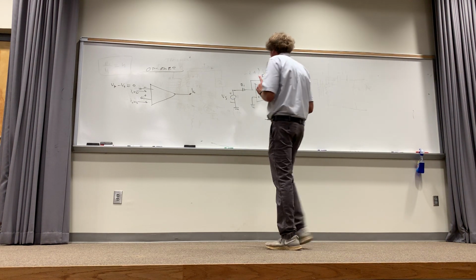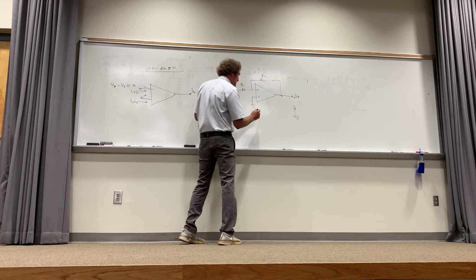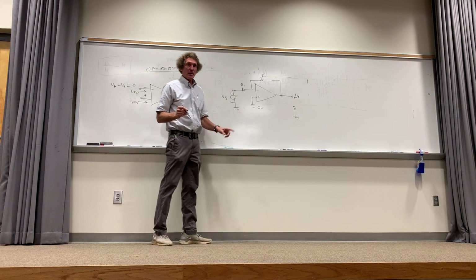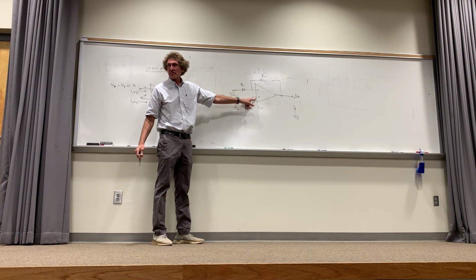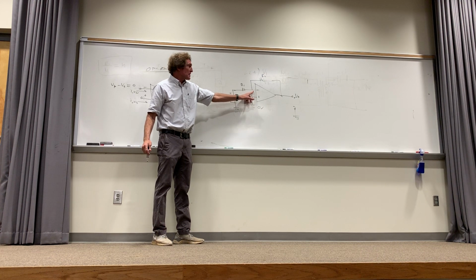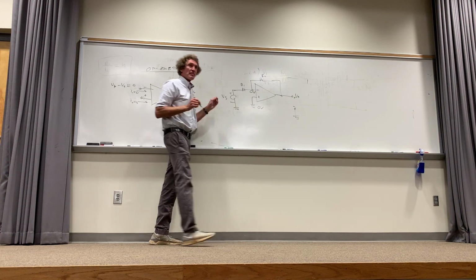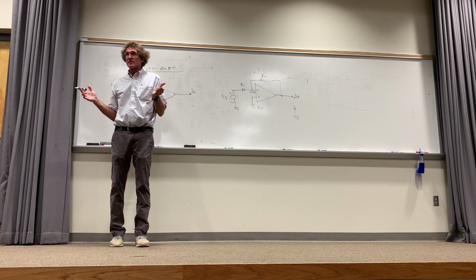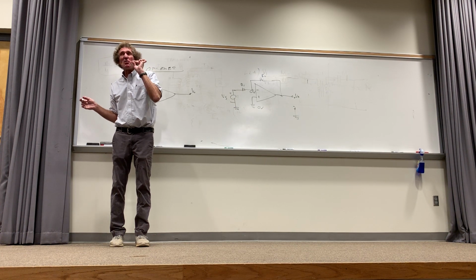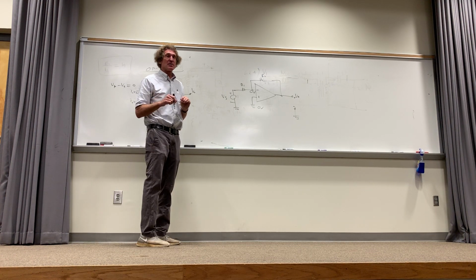Now here's how it works. If there's no voltage across it, what is the assumed voltage at ground? 0. So that's 0 volts, right? Do you agree there's 0 volts at the positive terminal? You all see this, class? What's the voltage on the negative? 0 as well. So 0 volts there. Got me? It's like a ground, isn't it, class? But you can't put a ground there, or this whole thing falls apart. There's actually a very small voltage there, but it's not anything appreciable.